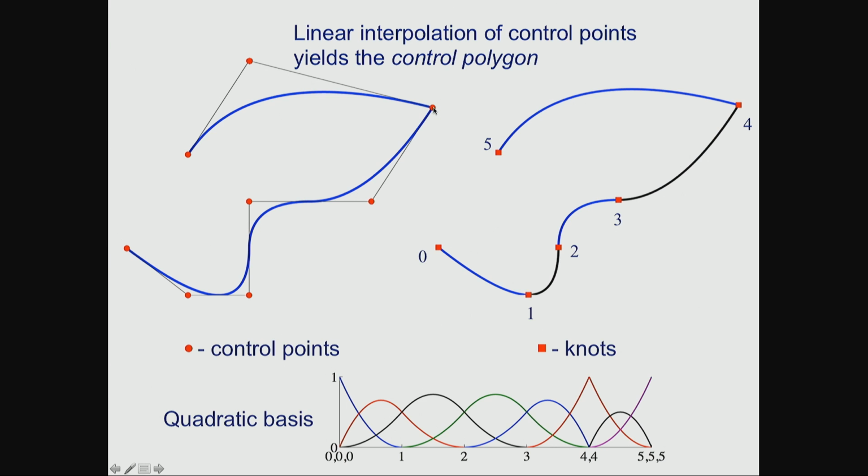Now, there's a dual point of view here, too. This is the design point of view. If I tug on a control point, I will change the design monotonically. Obviously, that's what you want in design. You don't want oscillations. When you're dealing with higher order C0 finite element functions, if you start moving a point, you can create oscillations.